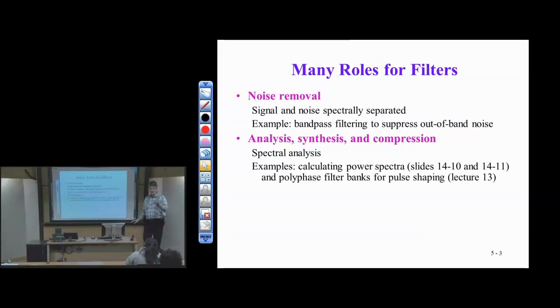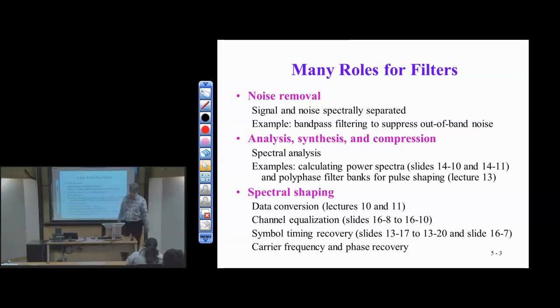In both cases, our visual system is low pass. So we can compress a signal simply by not encoding, at least very many bits anyway, high frequency information. It's not as important as the low frequency information to our human visual system. So we can use filtering to aid compression, and we do in practice in standards. This is in JPEG, for example. It's in MPEG.